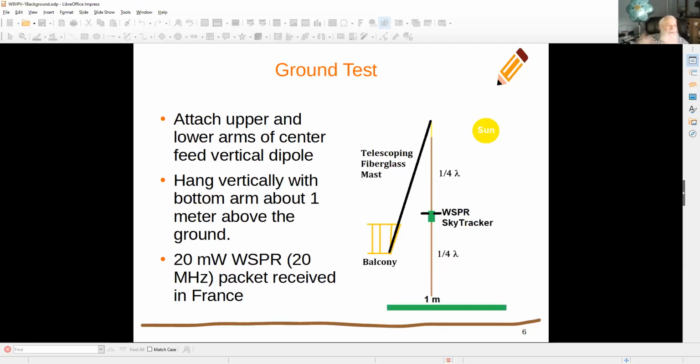So we knew that the system was very, very successful here. We weren't going to have any problems. We'd taken even more time to cut the antenna. It was a little long, and we measured things precisely, and we cut the quarter wave parts of the antenna, cut about 1 meter off the wire that he gave us to get as good a match as we could. And of course, there's no feed line loss because there's no feed line. The transmitter is sitting right at the middle of the antenna.